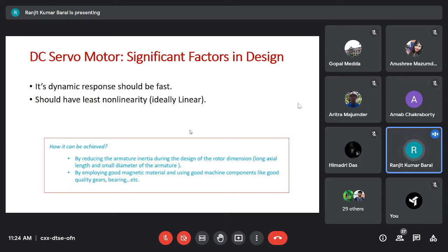but you can reduce the diameter, so that you can keep the moment of inertia smaller. So there is an optimization in the hand of the designer. So the designer will decide how much diameter should be reduced and how much length should be increased in order to keep the power output constant, depending upon various constraints. In order to reduce the cost, what will the designer do?